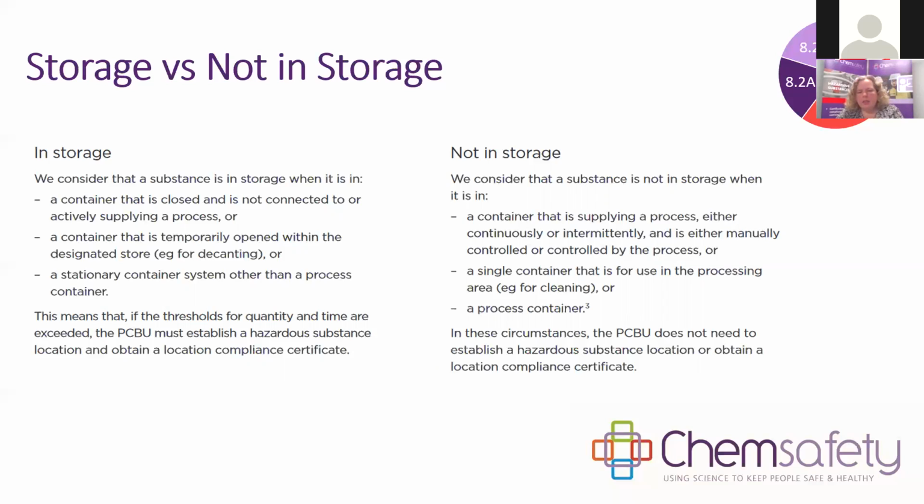On the other side of that, WorkSafe consider that a substance is not in storage if it's in a container that is supplying a process and that is either manually controlled or controlled by the process. So for example, you might have a dosing system that monitors the pH and then adds in a chemical to balance that as required. If it's a single container for use in a processing area, so you might have a 20-litre container or a drum of something that's there, that's used in that area, but it's not necessarily connected to something. Or if it's a process container, then it's not in storage, it's for use of something there.